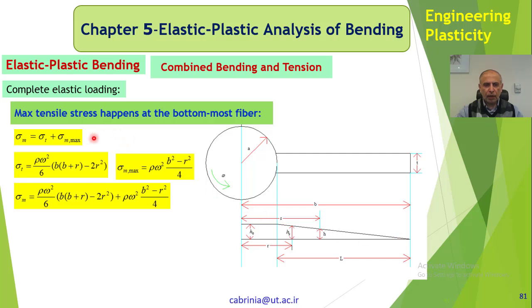Also, we have tensile stress acting on h2 due to the normal stress. So we have the sum of these stresses at the bottommost fiber, okay? Because when we come to other fibers at h2, it is a maximum. The bottommost fiber is maximum, and it is tensile, as I explained, because the unsymmetrical part of this section causes it to bend outwards like that.